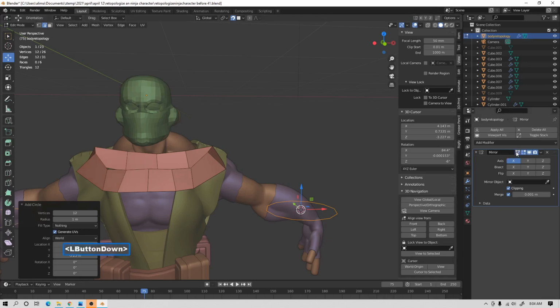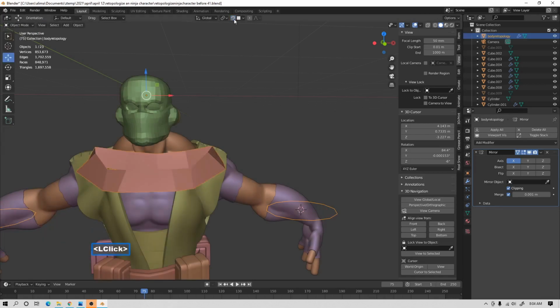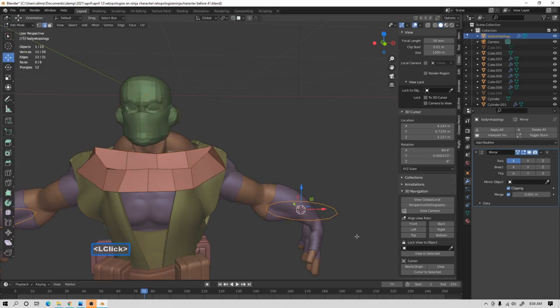I'm going to go to the right, select the triangle. I brought this in, right? Now I have snapping on. I didn't click anything yet. So this is an actual circle. However, as soon as I click something with this on, this will cause issues. So I'm going to go to the upper left, go to object mode, turn off this snapping, then go back to the upper left, go back to edit mode, so I can place this without issues.